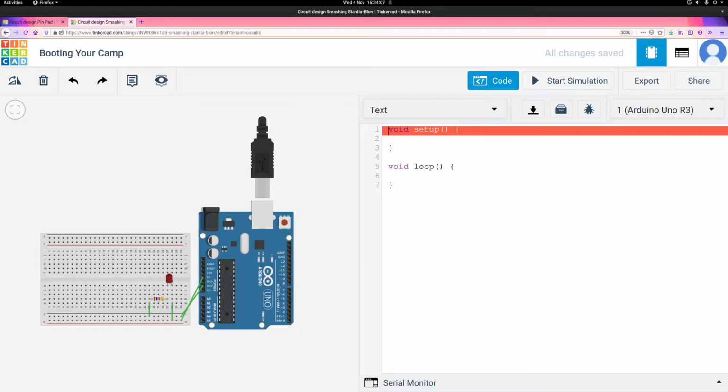And then, as was pointed out, the other highlighted line, sorry for my own ambiguity there, is a setup function. So Arduino is different from C++ in that it gives you these two special functions. Everything inside of these curly brackets gets run exactly once when the Arduino is first turned on, or every time you press this reset button.